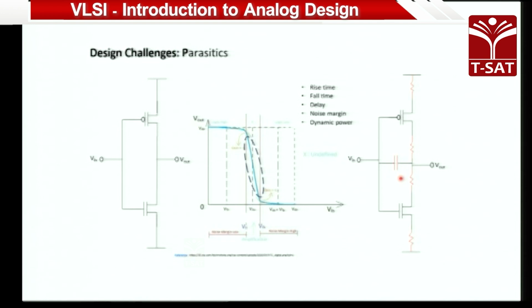So the components that you see in red are parasitics, and these come when the device is getting manufactured. There is a capacitor between the input and output, a resistor between the power supply and this net, and another resistor between these two nets. If you do not consider these three components, this characteristic will change and will not be the real characteristic. You are not considering the real factors coming out of parasitics.